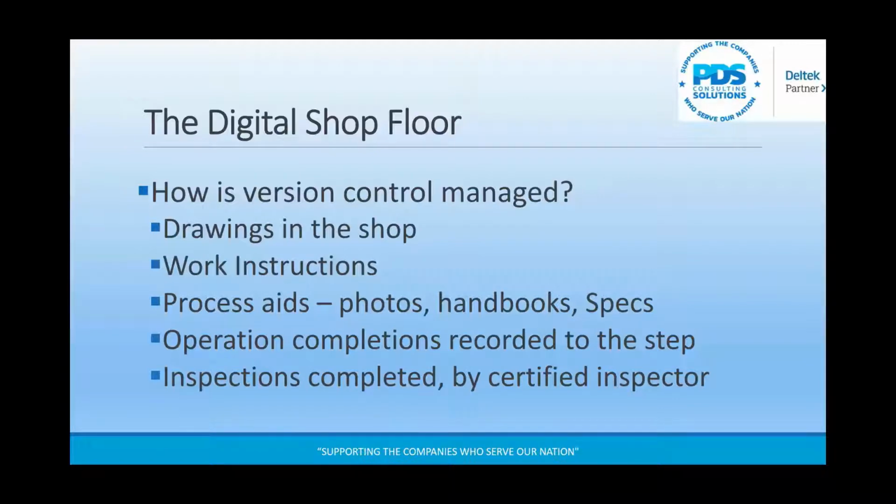It's not so long ago that I remember finding technicians that had squirreled away their favorite drawings with all the markings and everything, and they tucked them away in a drawer hidden. So the next time they built that unit, they pulled out their favorite drawings instead of using the official drawings from the vault. So where are you managing version control on your drawings, whether it's a customer provided drawing or an internal design department? How do the drawings get to the shop? What validations are in place to make sure those are the actual drawings that are being used during the assembly or integration steps? And going along with the drawings, what kind of work instructions do you have?